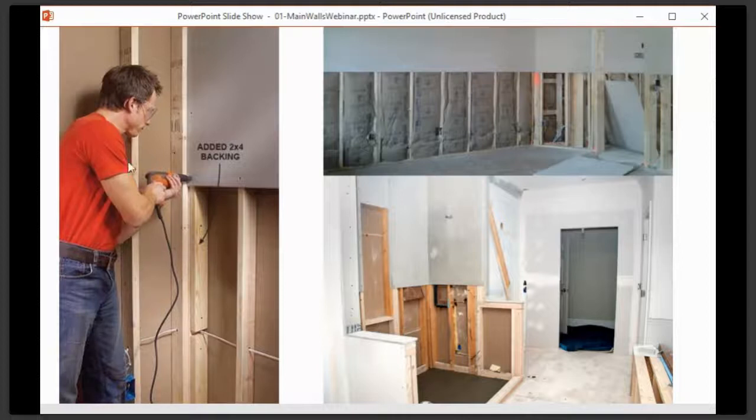So generally speaking, if you have a completely hollow wall, it's not going to be that good at blocking sound. However, you can add insulation. Insulation is very good for that. You can buy boards, which will be covered in the lesson on materials. There are different types of plasterboards that you can purchase. Some of them are fire retardant. Some of them are more suitable for areas of high condensation, such as bathrooms. And there are also some with stronger soundproofing abilities.